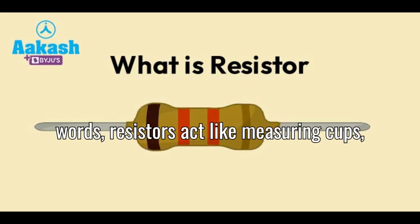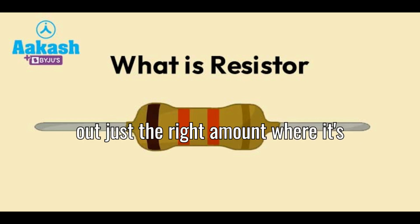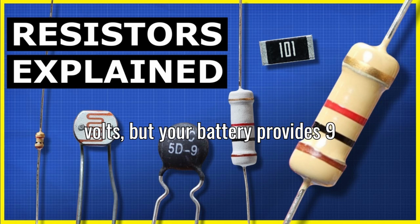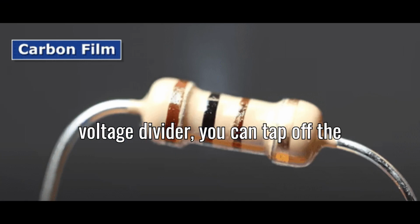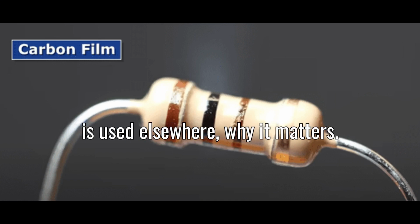In other words, resistors act like measuring cups, taking a large jug of voltage and pouring out just the right amount where it's needed. Real-life example. A microcontroller might only need 3.3 volts, but your battery provides 9 volts. By arranging two resistors in a voltage divider, you can tap off the smaller 3.3V portion while the rest is used elsewhere.